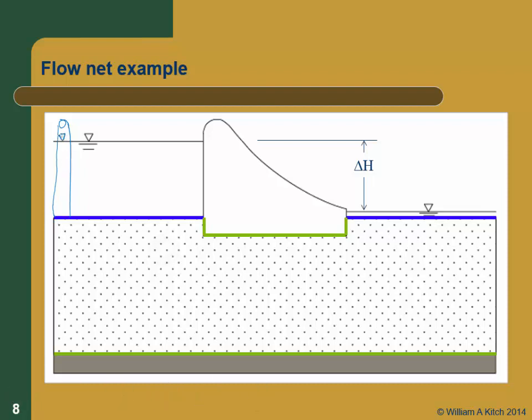Right up to the top of the lake. And I put one here. Where's the water going to rise to? Right up to the top of the lake. So every piezometer I put there right at the surface, the water's going to rise to the top of the lake, right? So what's constant along that blue line? The total head is constant along that blue line, because the height above the end of the piezometer, where the water rises to, is the total head. So that's an equipotential line, right? This is equipotential.